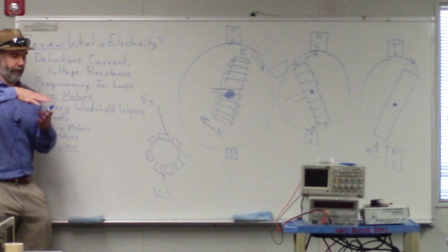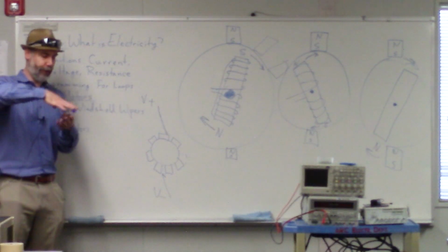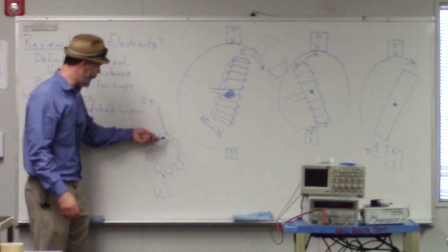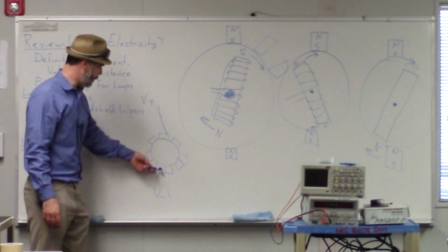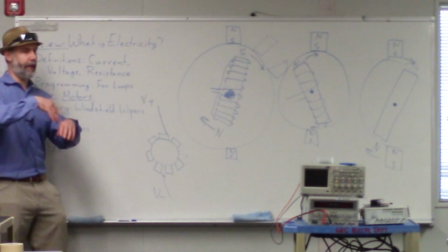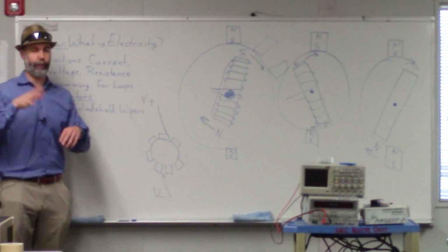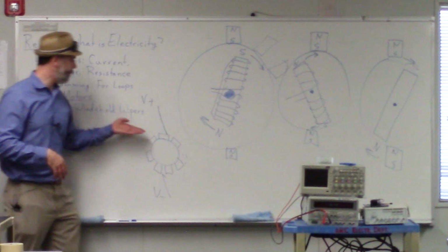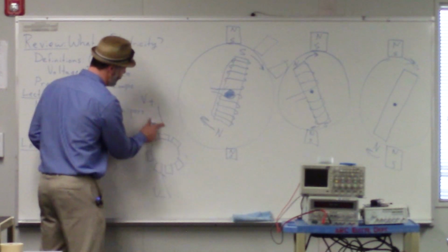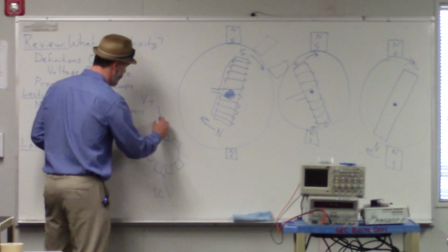They were literally metal brushes with lots of little tines that would touch these metal connections. But they found that these tines had a tendency to break off and wear out over time. So now these connections are usually made with blocks of graphite.